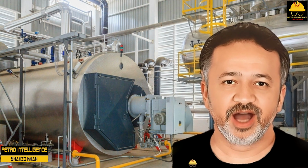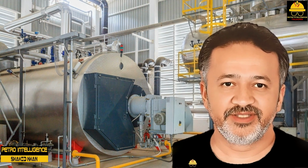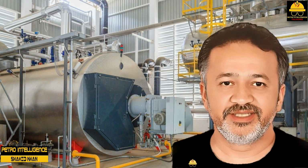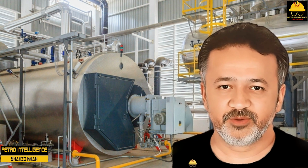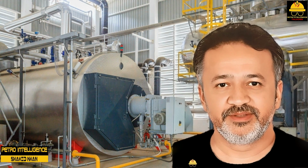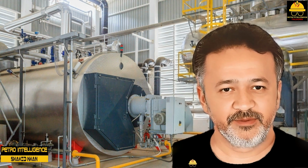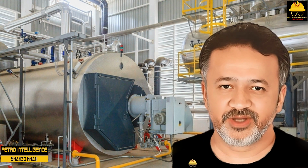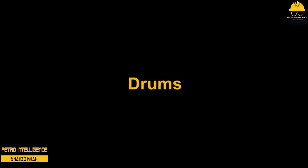Steam is removed from the upper steam-generating drum and heated to the desired temperature in superheater tubes. Superheated steam temperature can be increased as it re-enters the furnace. Some processes cannot handle high temperatures, so the superheated steam is cooled off. This process is called desuperheating.